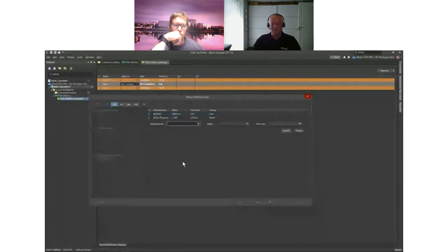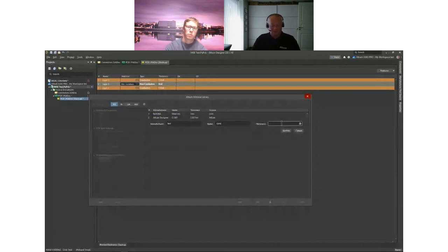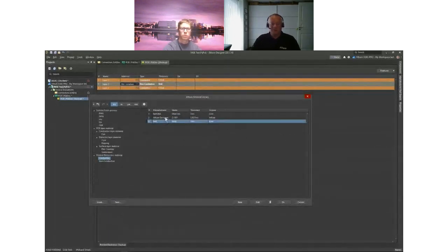Give it a name, Test, for instance, and let's say that this is gold, and a thickness of 1 mil. Simply click update here, and then you have the option to use that one also. You should then, of course, save this one somewhere where your team can also access this material library that you just created.